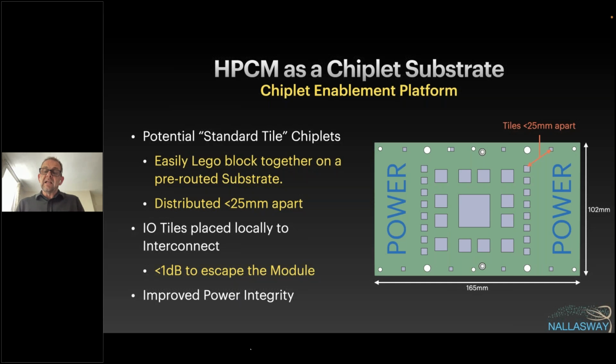Alan, NVIDIA just did a paper where they did 50 gig across, I guess an XSR or whatever. I don't want to use that particular term, but that was talking about 0.3 picojoules per bit, right? So yes, that was Grace Hopper, where they had the Grace package right next to the Hopper package, and it was 1.3 picojoules per bit for them to go, compared to PCIe at 7 to 10 picojoules per bit. So there's obviously, with some innovation, a capability to go. That was a very short distance to get that power, right? Yes. I just saw the announcement a couple of days ago. But there's definitely.